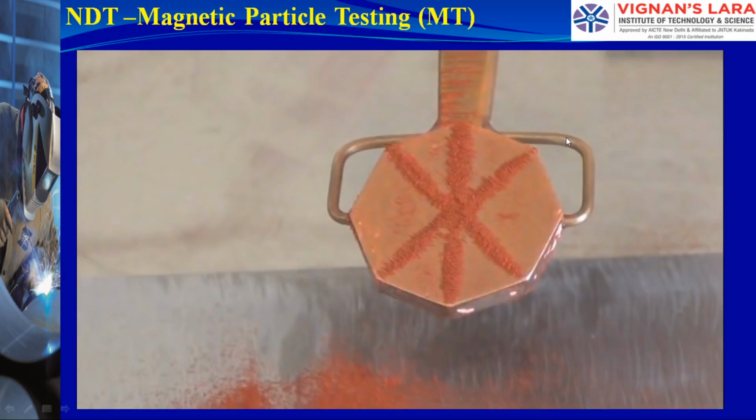Now we are ready to do the magnetic particle inspection on these two plates. We place the yoke, apply the dry particles, and have the yoke on. And then I will use the blower to remove any excess particles. And you can see the indication starts to show up. Here is the indication in this plate, right at that location. The indication is about 6 to 7 millimeters long, and it's very clear, which is right here.